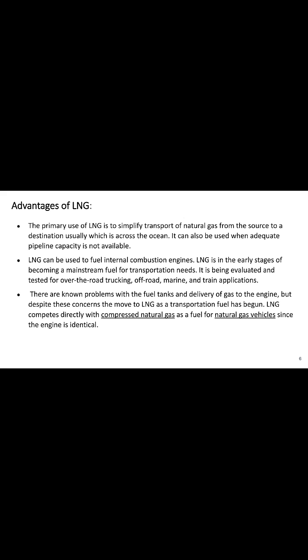LNG is in an early stage of becoming a mainstream fuel for transportation needs. It is being evaluated and tested for over-the-road trucking, off-road, marine and train applications. There are known problems with the fuel tanks and delivery of gas to the engine, but despite these concerns, the move of LNG as a transportation fuel has begun. LNG competes directly with compressed natural gas as a fuel for natural gas vehicles since the engine is identical.